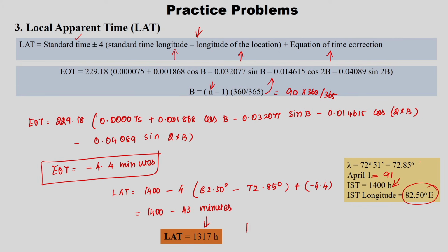So, here we finished the first problem. In the first problem we were given a flat plate collector of inclination beta 30 degrees, with phi given as 19.28 degrees and lambda as 72.85 degrees. With this location, for beta of 30 degrees on April 1st at 10 hours of local apparent time, we calculated the angle of incidence, which is 33.29 degrees.